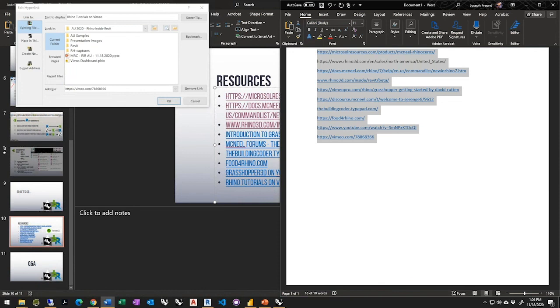And in addition, Grasshopper has a connection to Tekla and a connection to Sofistik. So if you wanted to, for instance, get the geometry out of Revit and into Tekla for precast, or you wanted to go out of Revit into Sofistik to do analysis of the reinforcement, that's been done a lot lately, with all these new connections of Rhino Inside, lots of different things.